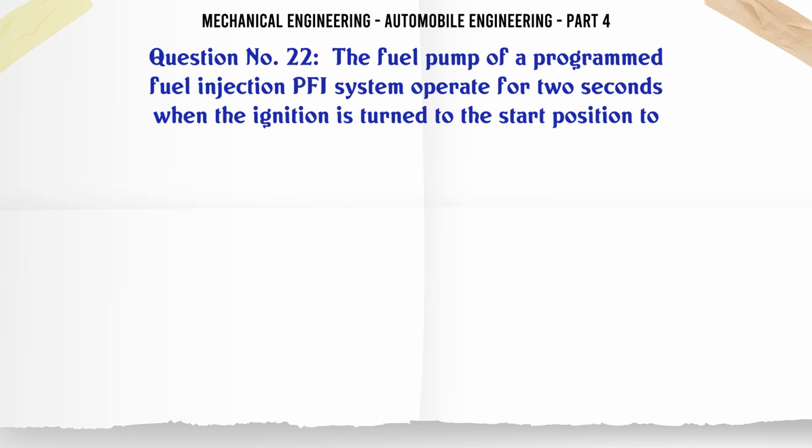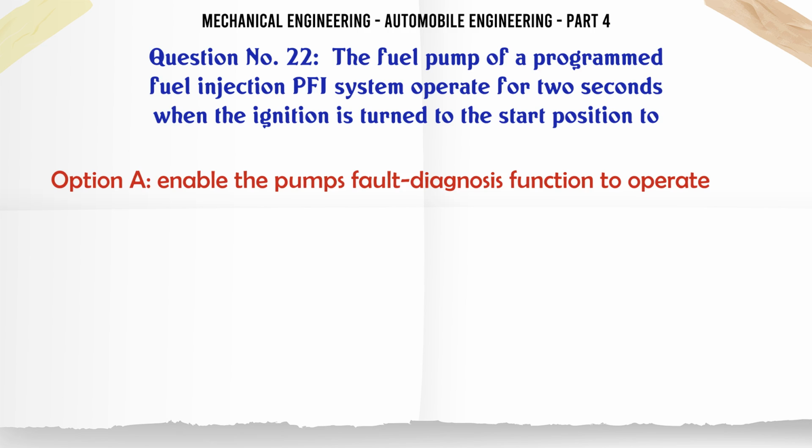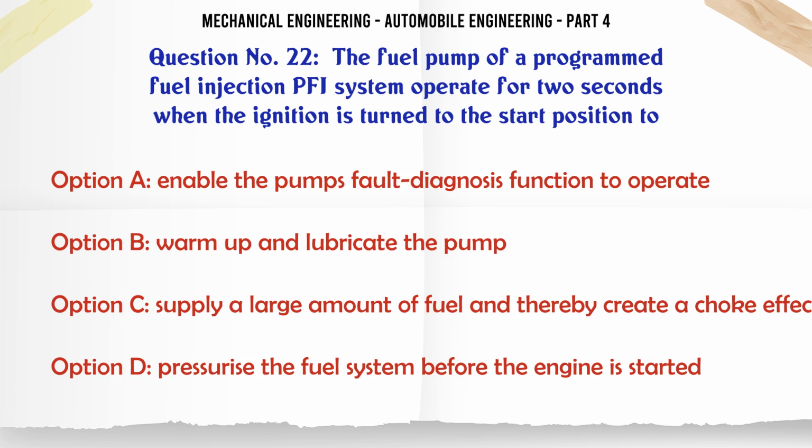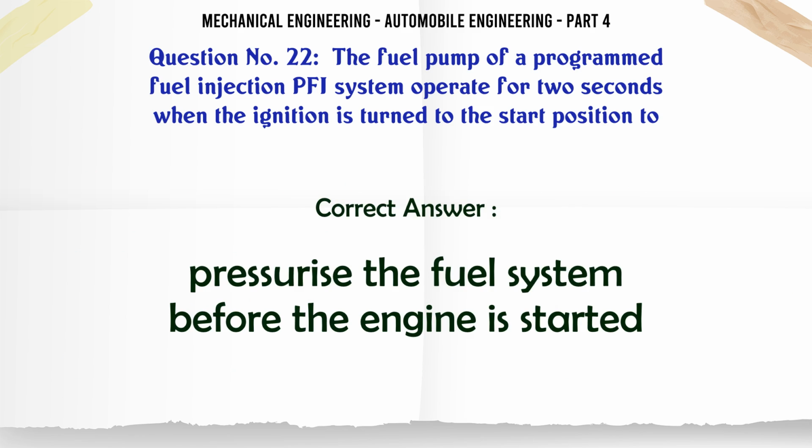The fuel pump of a programmed fuel injection PFI system operates for 2 seconds when the ignition is turned to the start position to: A. enable the pump's fault diagnosis function to operate, B. warm up and lubricate the pump, C. supply a large amount of fuel and thereby create a choke effect, D. pressurize the fuel system before the engine is started. The correct answer is pressurize the fuel system before the engine is started.